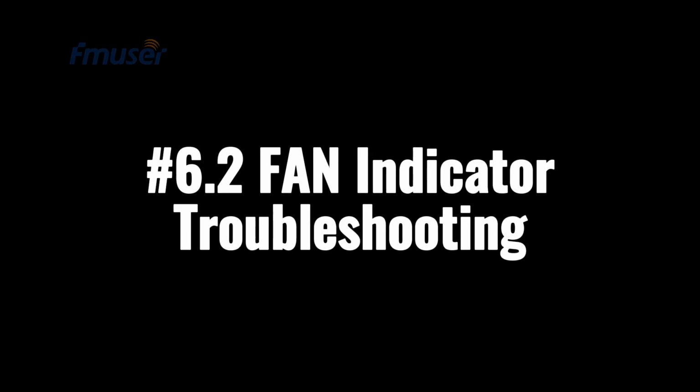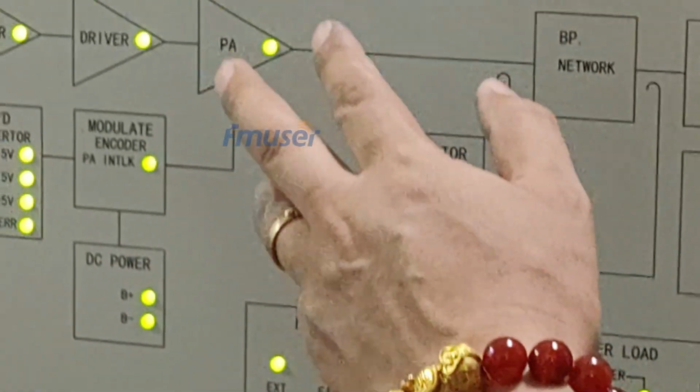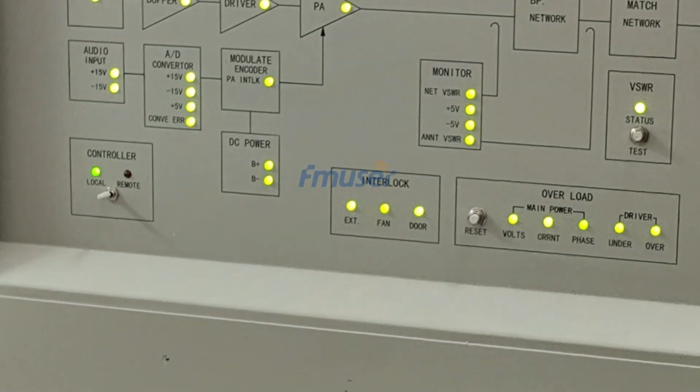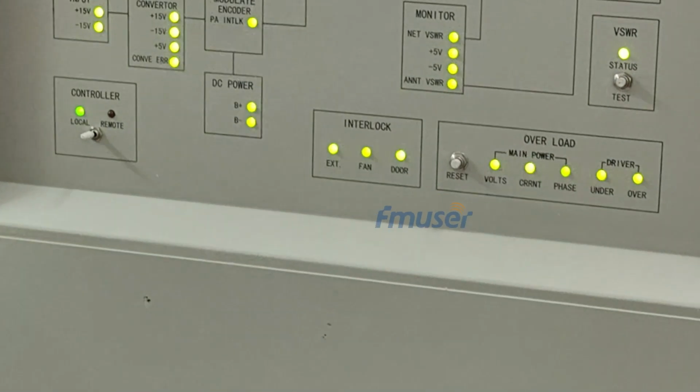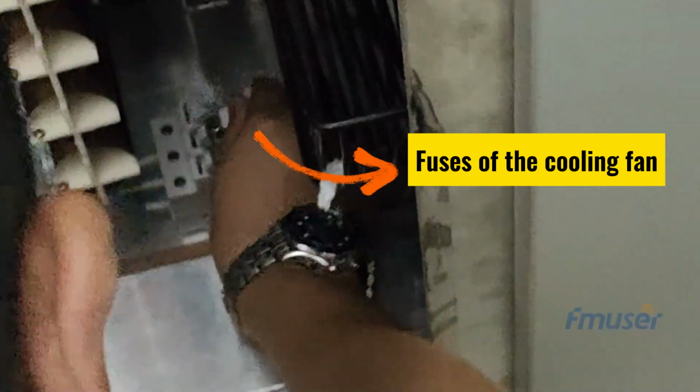Fan indicator light troubleshooting. The fan work indicator light is responsible for indicating the normal operation of the fan integrated into the transmitter. To test the status of the fan indicator light, we can simulate a fault by removing the fan fuse and powering on the transmitter. However, it is crucial to note that it is extremely dangerous to operate the transmitter without a functioning fan. In such cases, the heat generated cannot be adequately dissipated, potentially leading to damage.